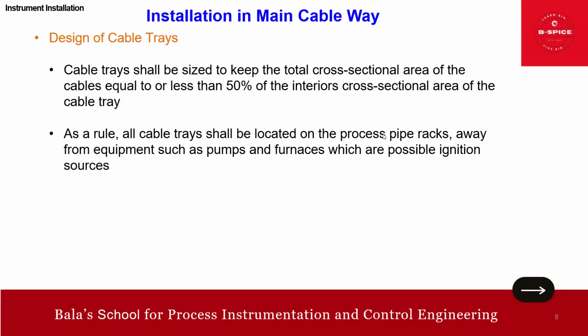This is what I just explained, on the process pipe rack, away also from equipment such as pumps, furnaces, which are possible ignition sources. We should always keep away from these ignition sources. So this is about the design of cable tray.